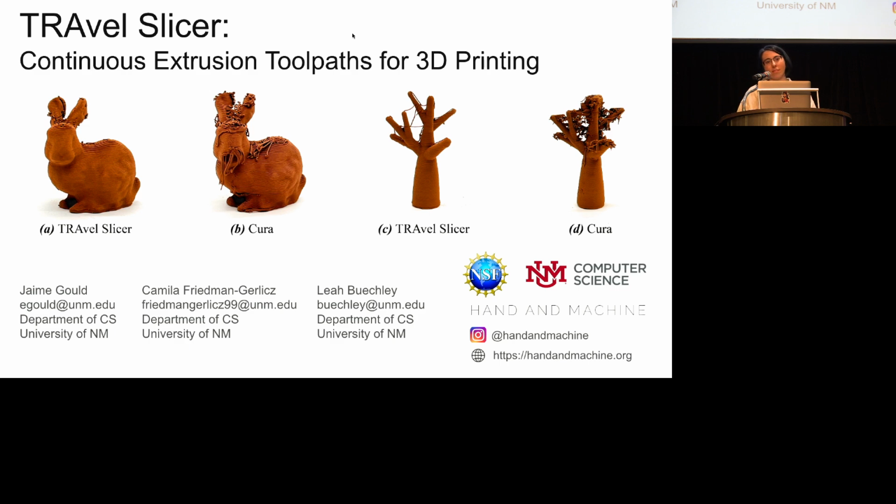Any other question? Even if you don't have the long nozzle, maybe you cannot save too much, but you can still apply that. You can, yeah. It's a much shorter distance, so you're still going to get travel movements back and forth because it has to print the entire model within those sections. But you'll still get a benefit of that distance.